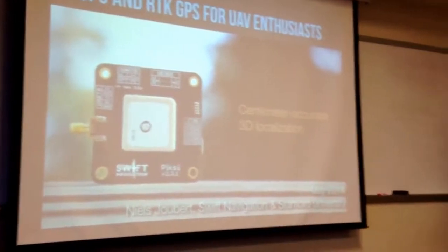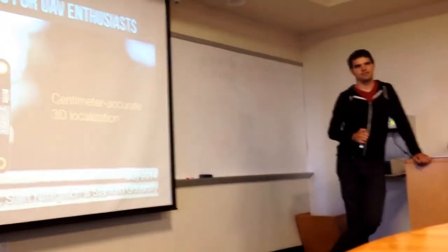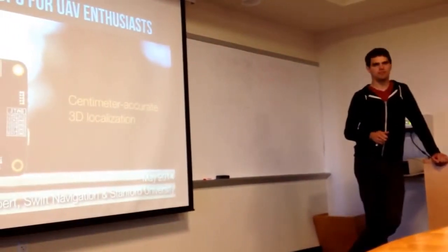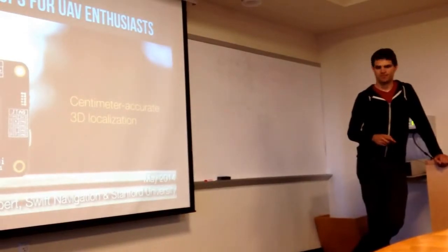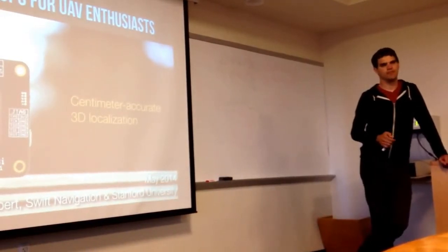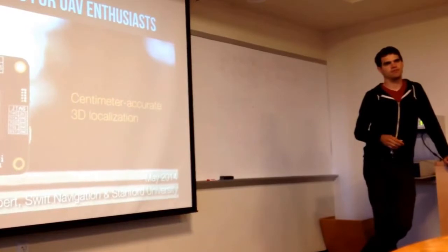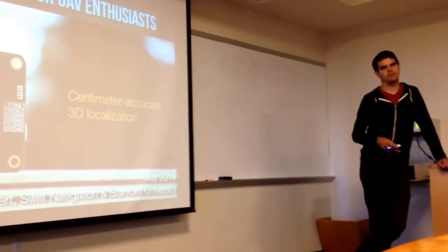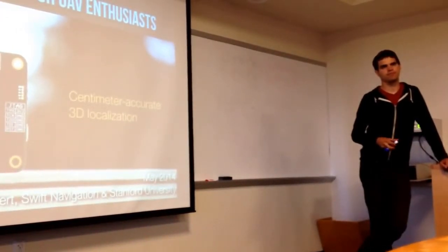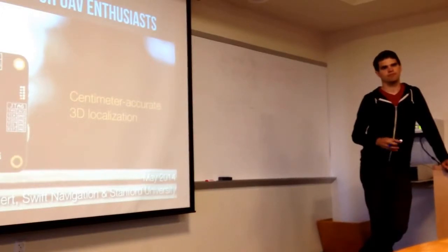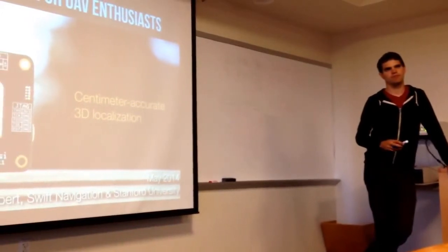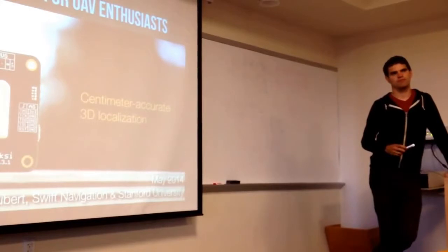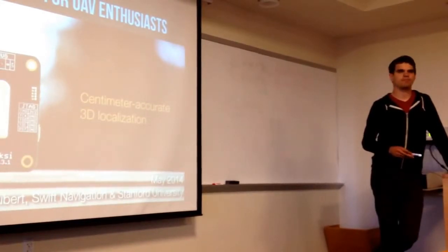I'm guessing this one's using both the carrier phase and the PRN. The carrier phase will give you the differential, and the PRN will give you a less accurate absolute position, right? Yes. Also, if you have say 50 different satellites with GPS and GNSS combined, each one with a different PRN, is your receiver actually generating 50 different PRNs all at the same time and checking to see if any of them are in range?